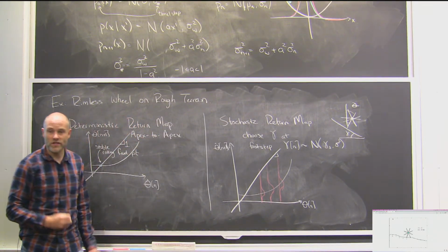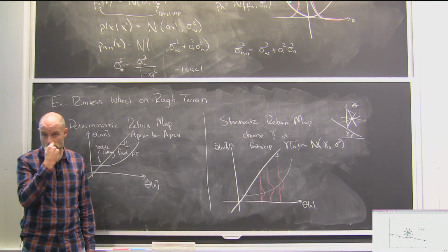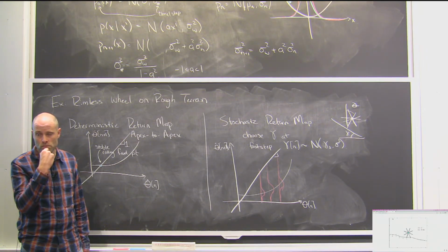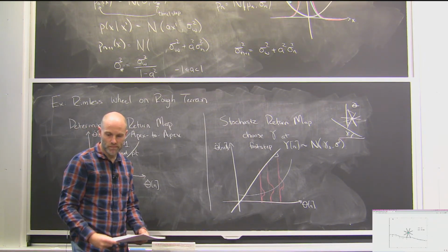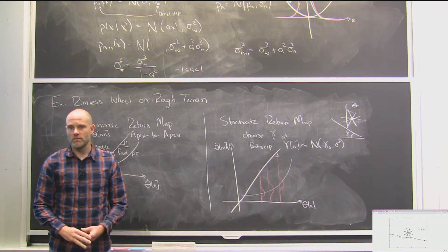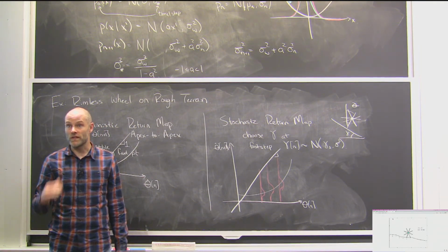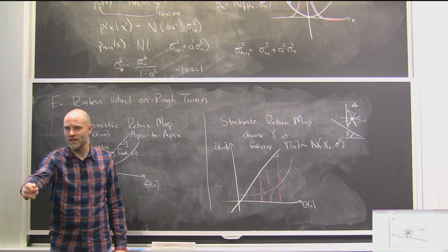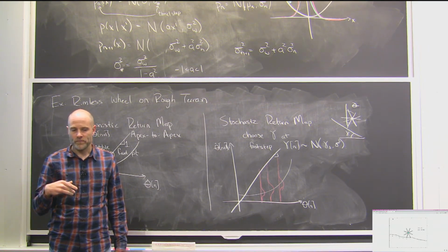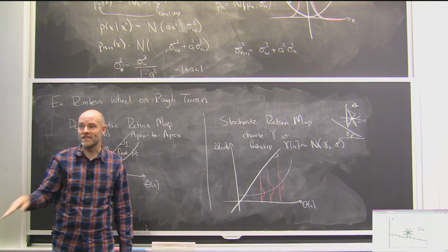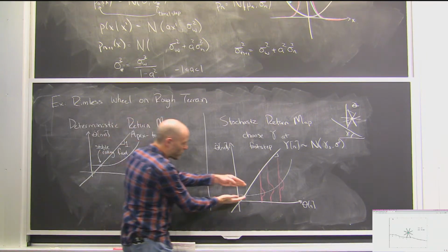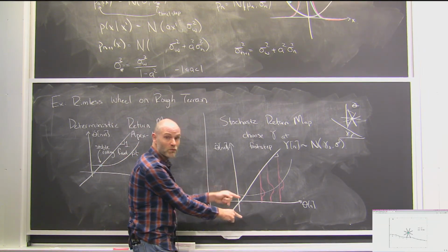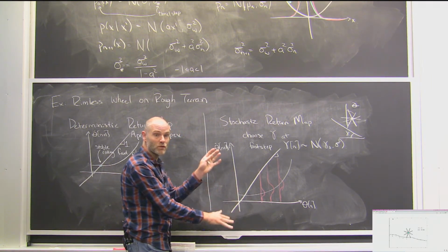All right. So what is the stationary distribution? What do you think? Every time somebody draws the ramp, am I going to come into the rolling fixed point? Maybe bounce around the rolling fixed point. What's the dynamics of this distribution going to look like? Eventually, someone's going to draw a piece of terrain or a couple small, flat enough terrains that I'll come to rest. The hope is that I have a long-living time transient where the stability converges around this fixed point in the deterministic system. But like my very simple example, it will slowly leak probability, like that balloon. It's going to slowly lose its probability and end up standing still.